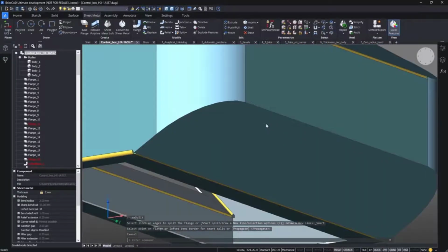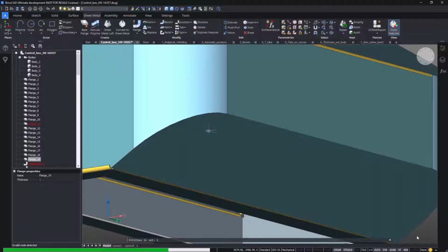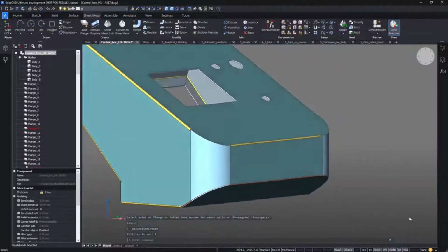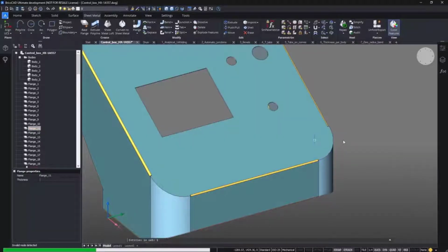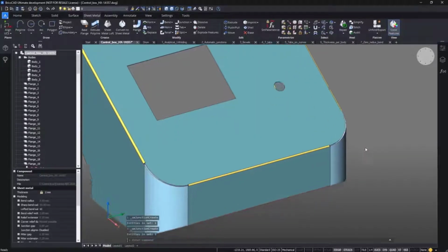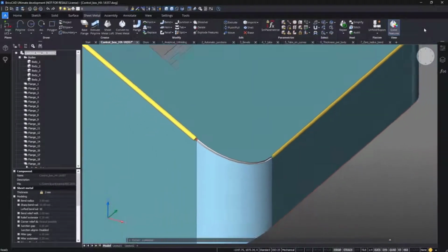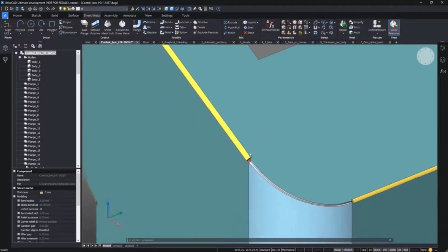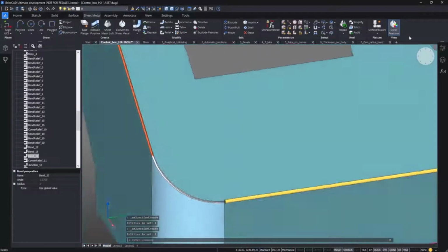Now, we create the curved junction on the bottom, on the top. There's still one choice to make for the part to be unfoldable, but thanks to the possibility to switch bends and junctions, we decide to open on two sides. The part becomes unfoldable.